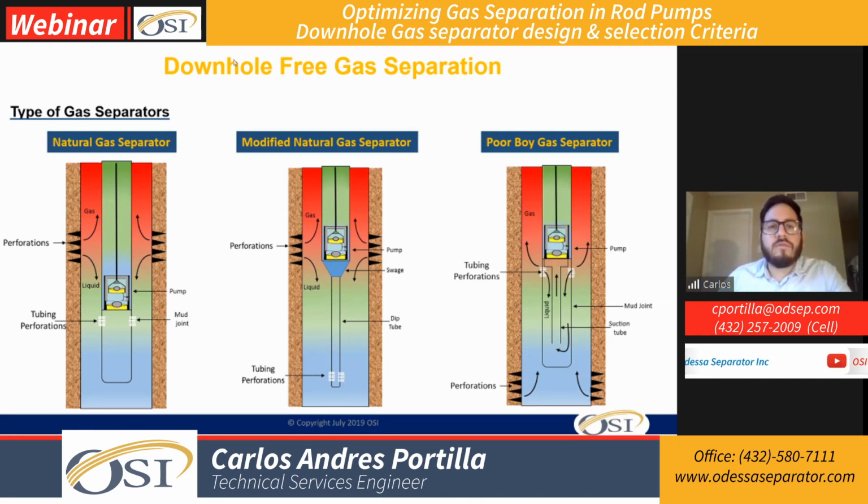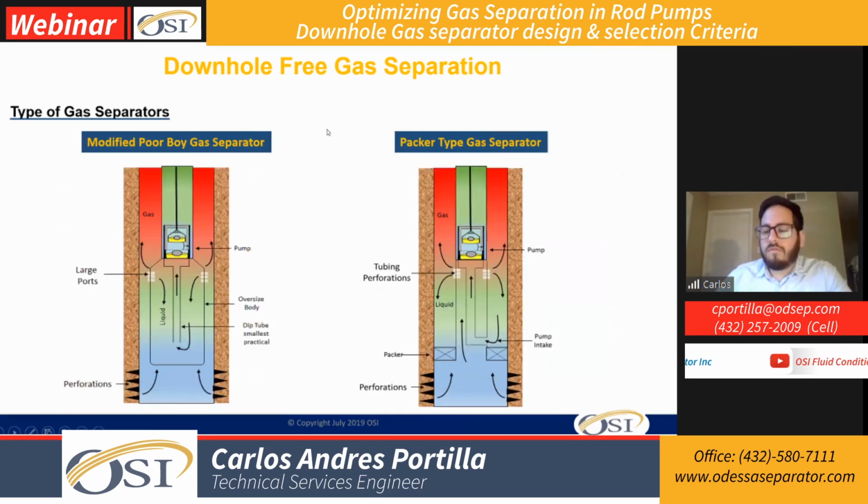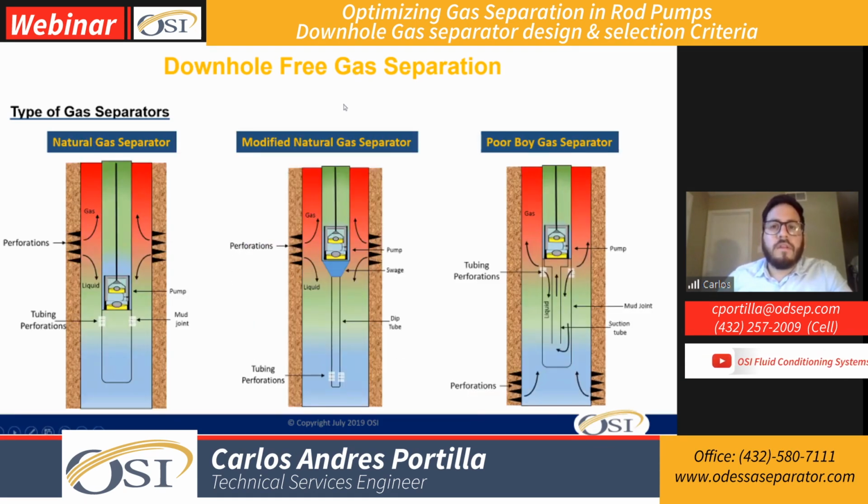The gas will be traveling, some of the gas, right, depending on what your pump speed is. The gas is going to start flowing upwards, okay? That's why, when we have gas problems, we recommend long strokes and low speeds, so we don't have high fluid velocity.